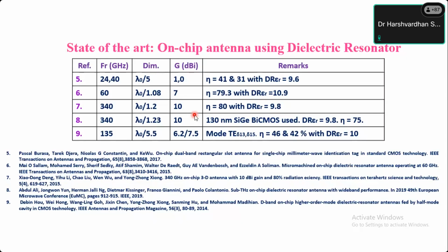The coverage area is very small because it has very little gain and efficiency. Also, the application is inside the chip, so we cannot put more power in to radiate. The chip generally works in microwatts, a few microwatts to 100 microwatts maximum, and we are not able to provide more power as input. So its applications are mostly as a receiver antenna.